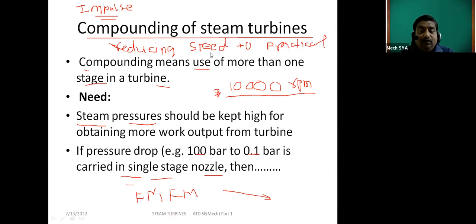In the impulse turbine, the pressure decreases only in the nozzle. The moving blade and fixed blade show symmetry in nature, therefore the pressure never decreases there and remains constant after the nozzle. But the velocity in the moving blades decreases because it is losing its momentum. Now there are three types of compounding methods. Can anybody mention them?